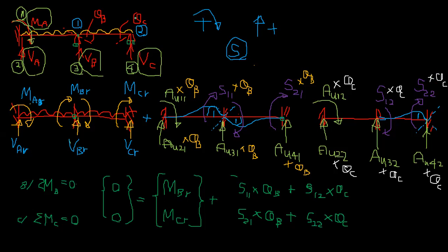So what we basically do is, just see, there are redundant two displacements, theta B and theta C. We make them 0 on purpose. Then we apply each at a time, but we apply only a unit displacement. Then we get the outputs and we multiply them by the original values. That's what we do here and here, right? And once these three structures are added together, we get the original back, right?